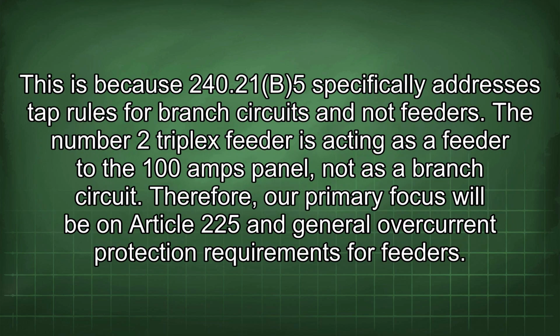This is because 240.21(B)(5) specifically addresses tap rules for branch circuits and not feeders. The number 2 triplex feeder is acting as a feeder to the 100 amps panel, not as a branch circuit. Therefore, our primary focus will be on Article 225 and general overcurrent protection requirements for feeders.